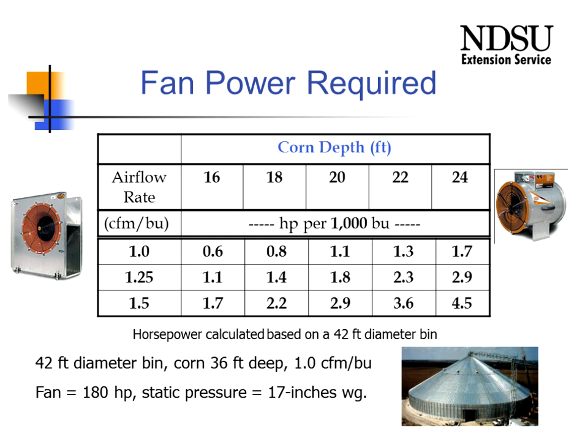Of course, that isn't realistic. It isn't practical to put that kind of horsepower on a bin. So if they're going to do natural air drying, ambient air drying in a bin, we really do need to keep that depth down to roughly that 20, 22-foot depth to stay energy efficient.